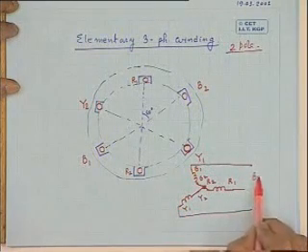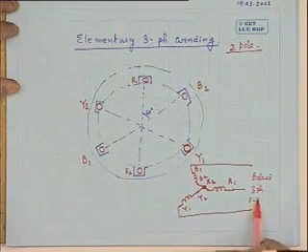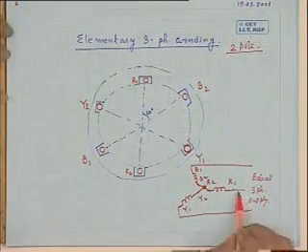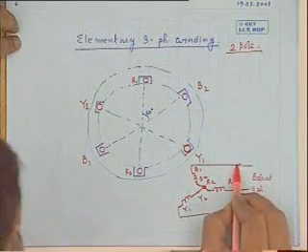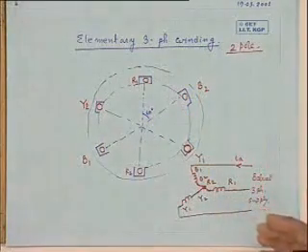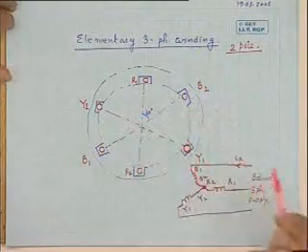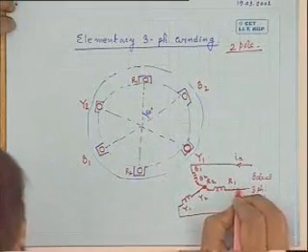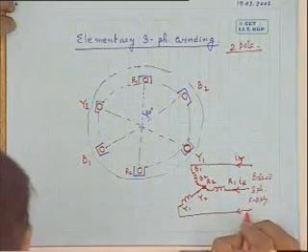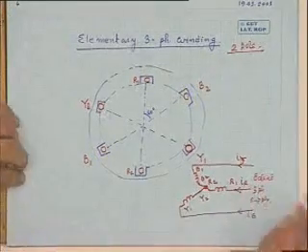And here these 3 terminals I will give a balanced 3-phase supply. Now a balanced 3-phase current will be drawn, provided the windings are identical in nature, R phase, Y phase, B phase. That is what it should be. That is, the number of turns in the R phase, Y phase and B phase are equal. So they will draw, say, this is IR, this is IY, and this is, say, IB, like this.